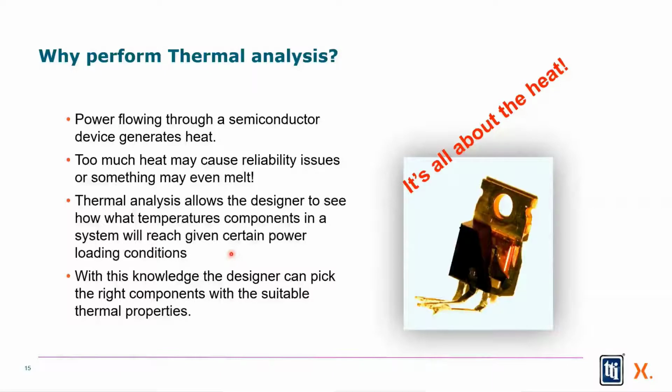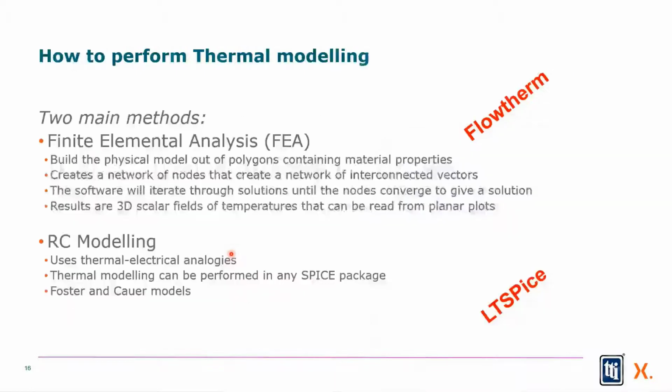When you use a power drill, how often do you normally turn it on? Well, it's not on 24 hours a day. It runs for a few seconds at incredible loads, and then it turns off and it has a period to cool. So that is the use of that application, and every application is going to have different use for it. So once you understand how long I have to drive so much current and how much time I have to cool it down, now it's possible that you can actually simulate that environment and understand how your design is going to work before you actually build it.